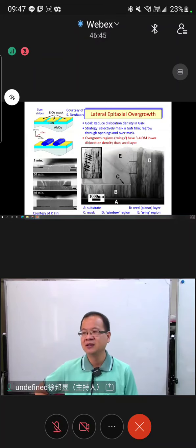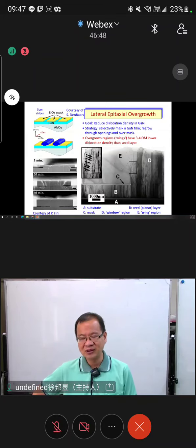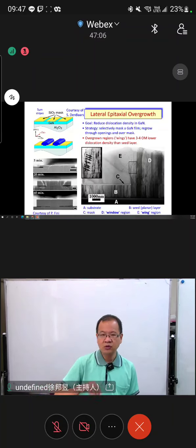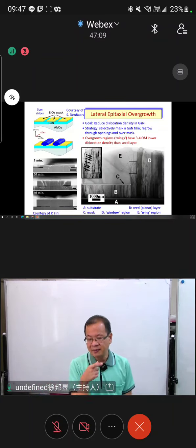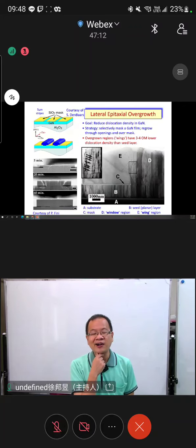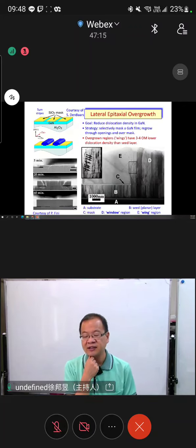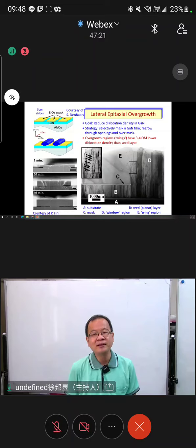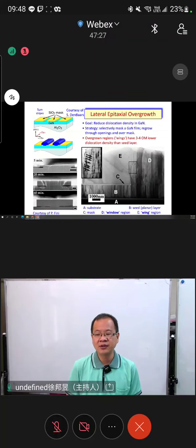Coulomb interaction is the most important and the most phenomenal driving force in this kind of structural growing, and most likely the strongest one in the natural world. It's so strong that you cannot control it well. That's why, if you look at the picture on the right side, the D and the B, you can see a lot of dotted lines, right? Those lines are dislocations. Look at the dislocations in the D part. So massive. You cannot control the crystal growing well. That's the typical problem for gallium nitride.